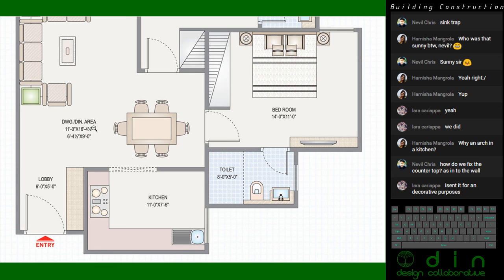So you have tiny walls that are made of brick, half brick thick, like, not 9-inch walls, some 6-inch walls, and you build them up, and then you place the counter on top of it, right? So the granite actually sits on top of that and is supported with the bricks themselves. If not, you can support the entire thing with plywood, which is what is done nowadays.